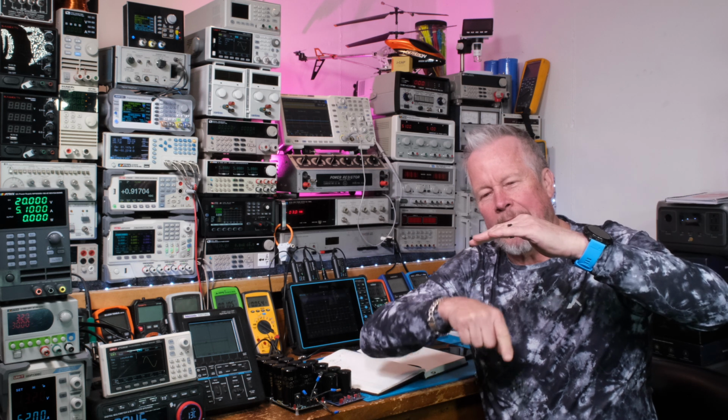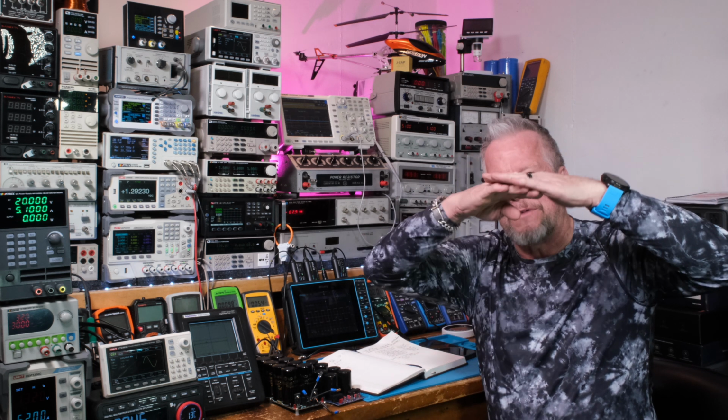When the rail is dipping down, I don't want them to hit each other, and flat top, because then your amplifier flat tops a little sooner, right? So if you can hold the voltage rail up higher so your amplifier output can come up without flat topping, hitting the rails, then you get more power, right?